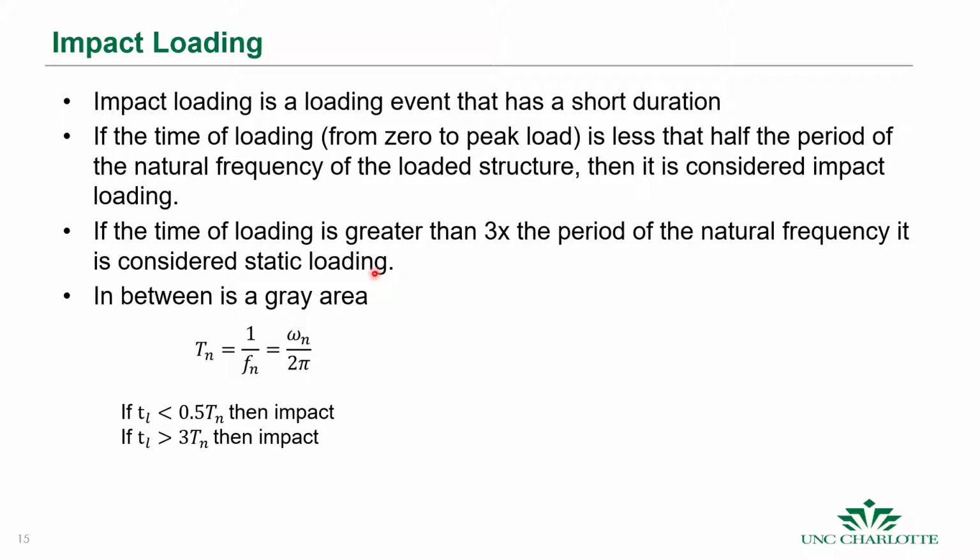So do we know if we experience an impact? Well, what we would need to do is maybe have some information about that structure, maybe do a tap test, and find out what its natural frequency is, or take a look at the first mode for the structure that you're looking at to see what the frequencies are of that structural system, and then you can compare that to how long the contact load is. So this may require some testing or some simulation or whatever for you to get that information.